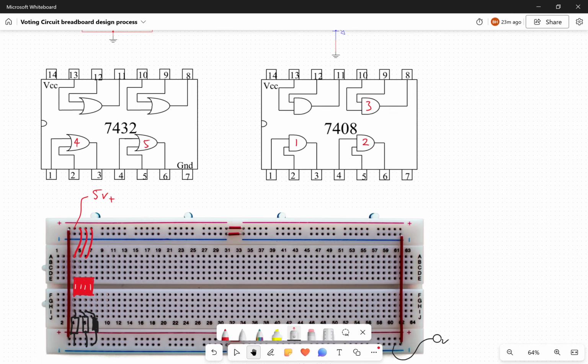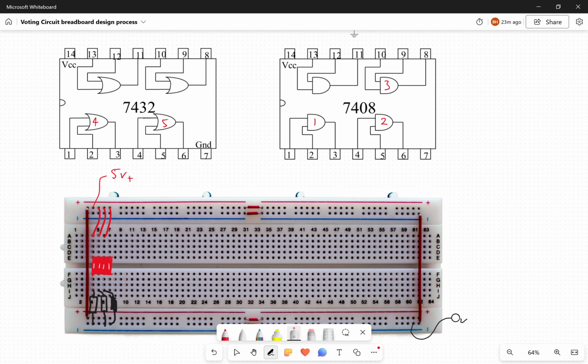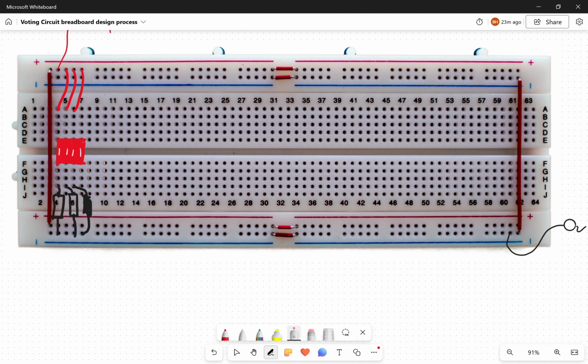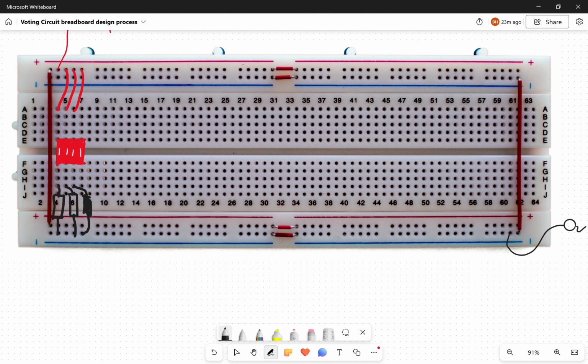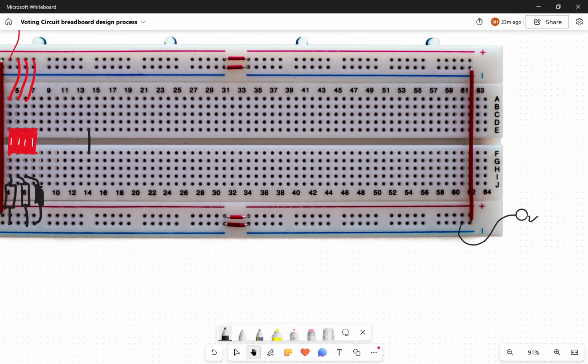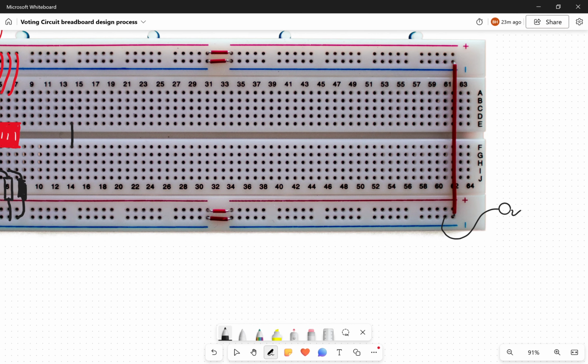Now for that we are using these two ICs, these 2 logic gate chips, and they've got 7 pins either side, 14 pins in total. So what we're going to try and do is give ourselves plenty of room, but actually sketch these in here. And this is where you're going to connect your wires up into those chips. So we're going to make sure they go across 7 ports of the breadboard. So 1, 2, 3, 4, 5, 6, 7. And then back across the other side.